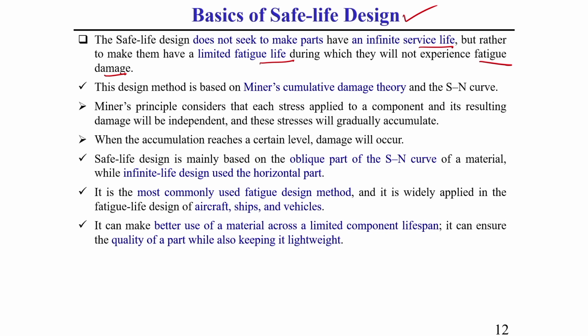This design method is based on Miner's cumulative damage theory and the S-N curve approach. So, this is a very important method. Here a very important technique we use for cumulative fatigue life calculation is called Miner's cumulative damage theory, and here we also use the S-N curve for prediction of the service life of a component.